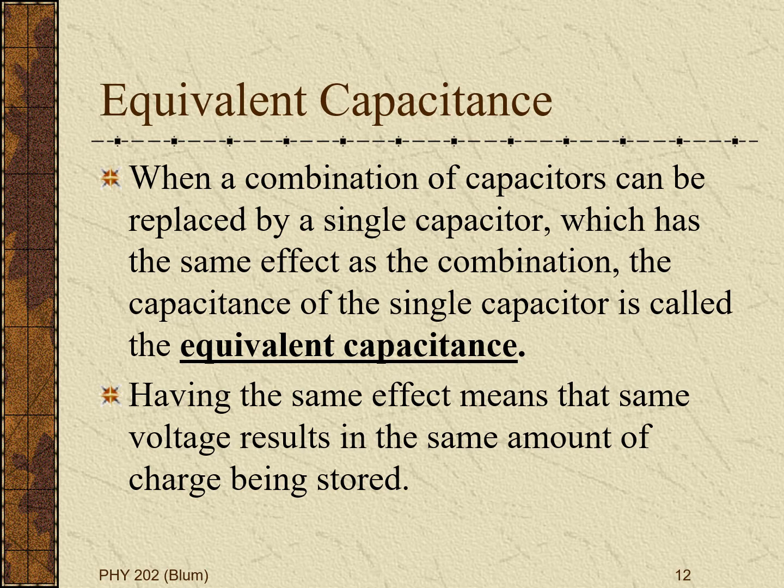And so in the resistor it was the voltage and the current that were the same, and in the capacitance it's going to be the voltage and the charge that are the same. So the equivalent capacitance will draw out the same charge for the same applied voltage as what it is replacing.